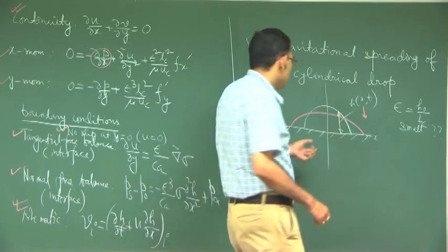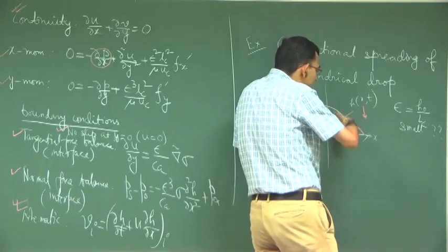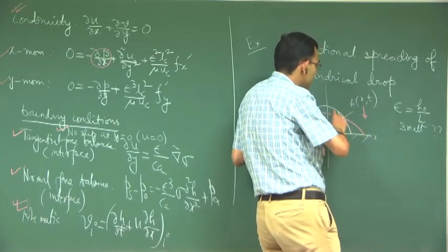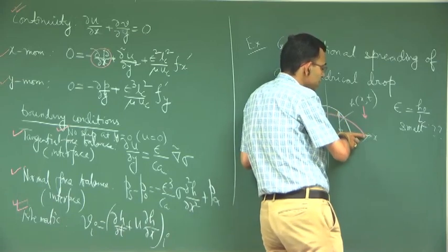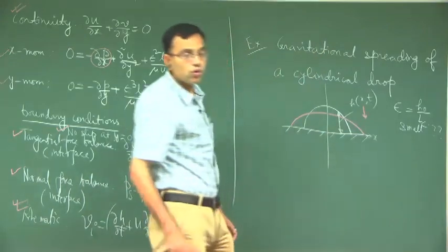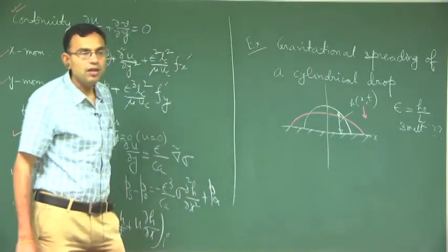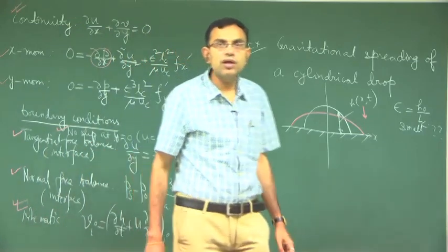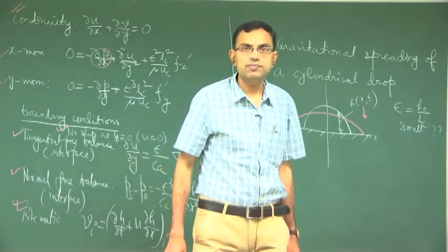Only when the spreading is towards the end of its journey will you have h much less as compared to L. So, only during that time can you apply the thin film theory for solving the film thickness.